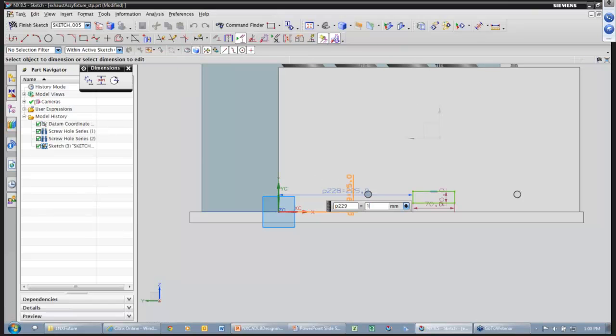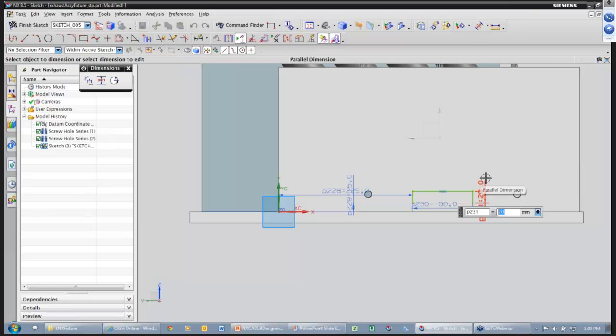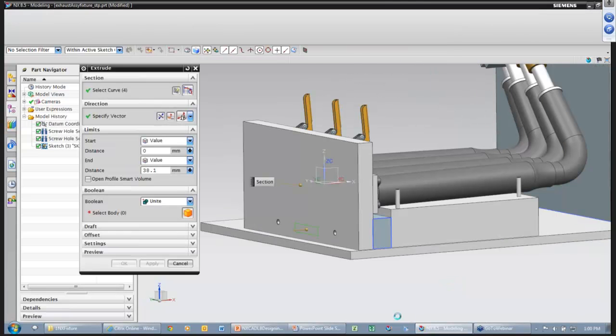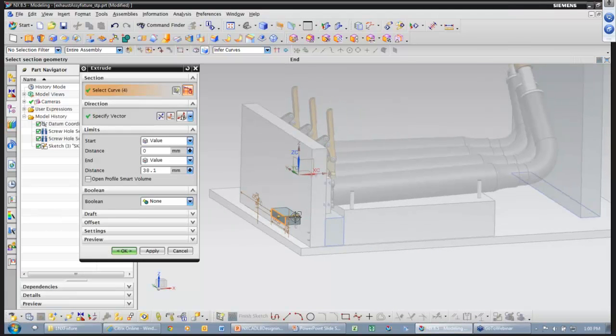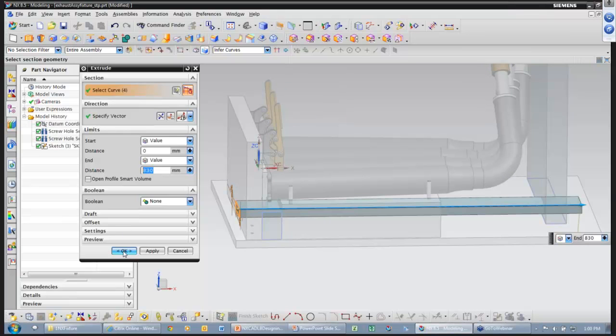And we'll put that. That looks good. Make that a little wider. Not that this really matters for what we're trying to show, just to go ahead and constrain this guy. That looks good. All right, so there's our sketch. So I'm going to go ahead and flip this. The Boolean should be set to none because I'm creating my own tool body here in the assembly.